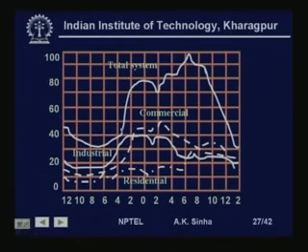our working starts, then the load goes up, and we will see that during the evening time we have a very large load. This generally happens mostly with the residential loading. This is what you are seeing as a residential load, that this loading becomes much larger during the evening when people have switched on their TVs, they are doing their cooking and all that, so all lights are on and so on. Whereas, if you see industrial load, it will be very high during the daytime.